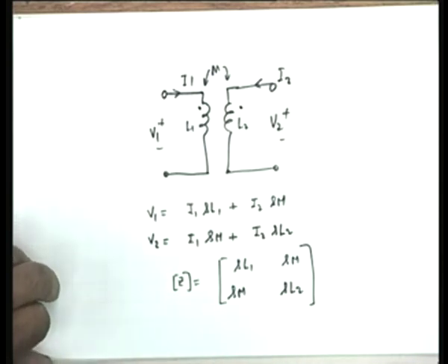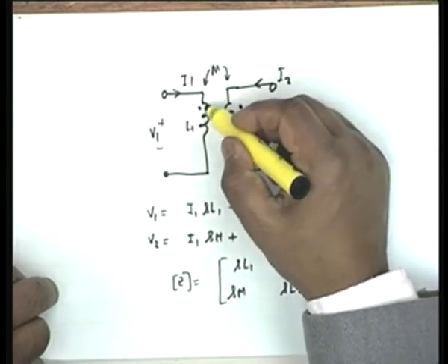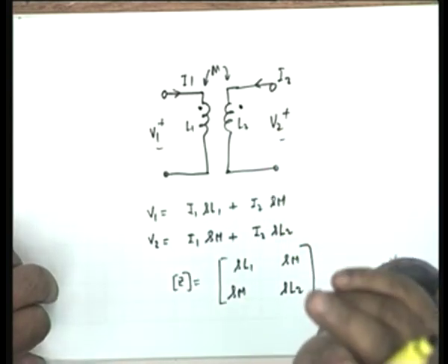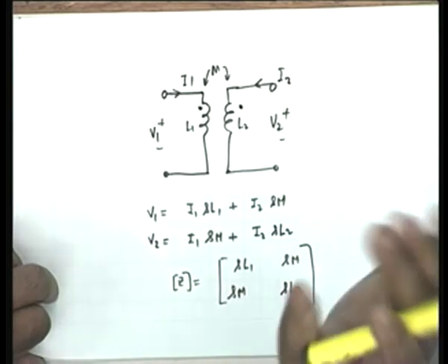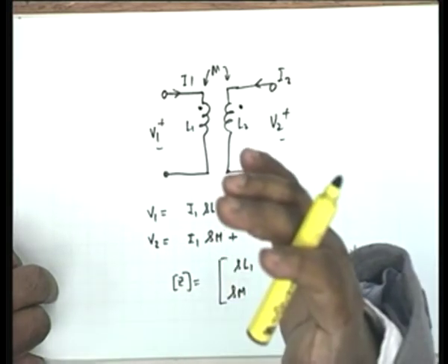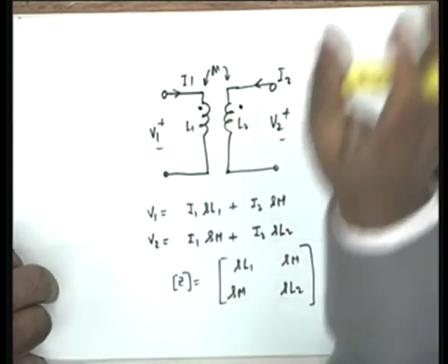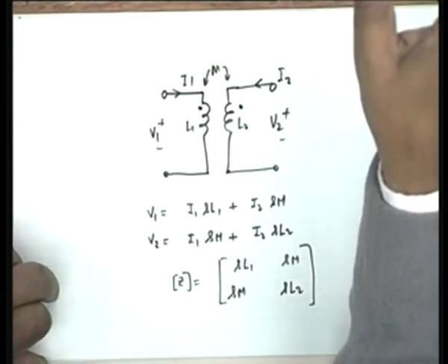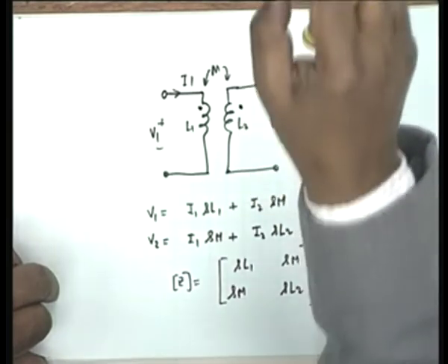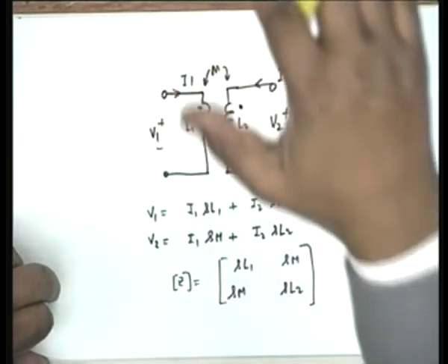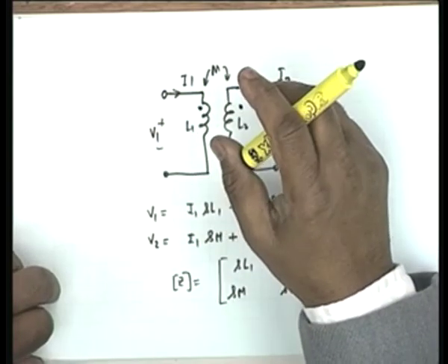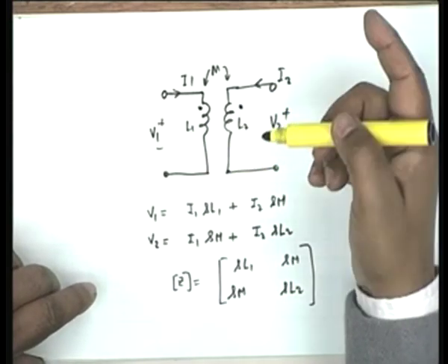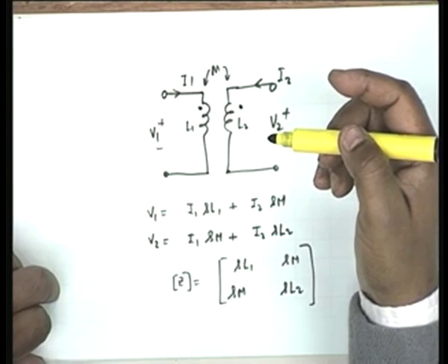Non-ideal in the sense, oh, that reminds me, what is an ideal transformer? Why is it called non-ideal? The L values are not tending to infinity, so it's a small one. If K is equal to 1 and the circuit is lossless, with no resistances, it is called a perfect transformer. Idealness is above perfection. Idealness implies that both L1 and L2 tend to infinity such that their ratio is finite. This is the definition of an ideal transformer.